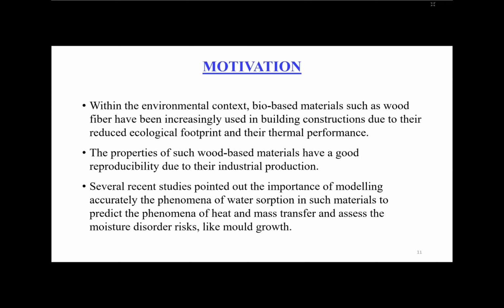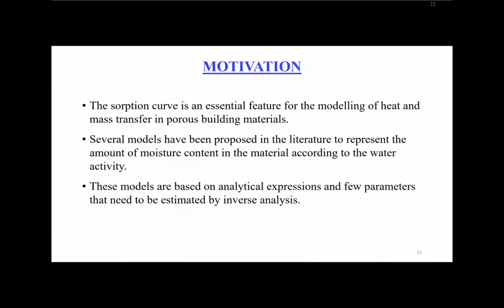However, several recent studies pointed out the importance of accurately modeling the phenomena of water absorption in such materials to predict the phenomena of heat and mass transfer and to assess moisture disorders like mold growth. So the sorption curve is an essential feature for the modeling of heat and mass transfer in porous building materials.